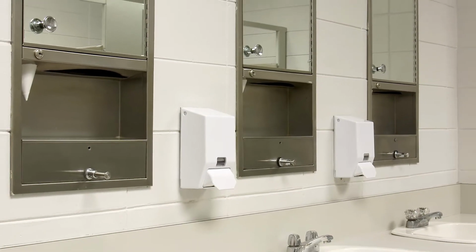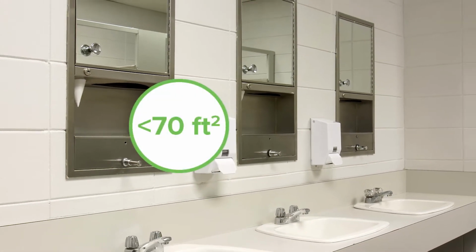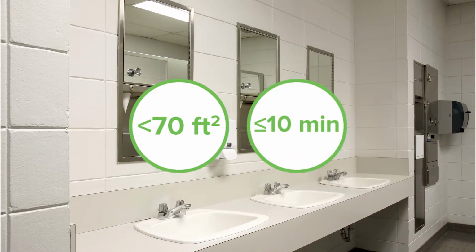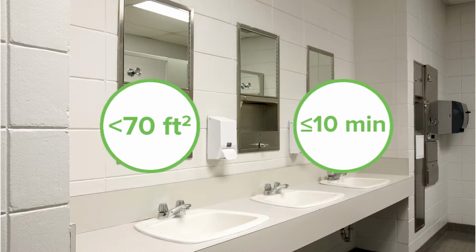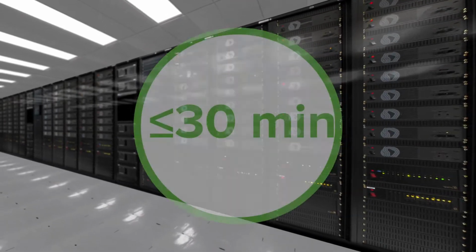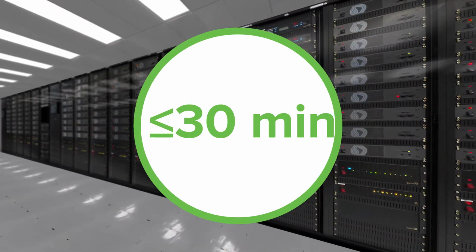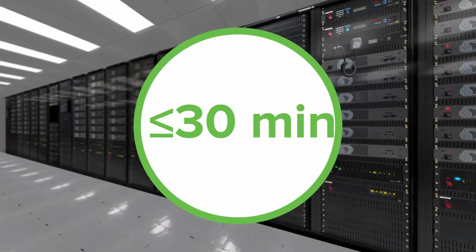Countdown timer switches can be used in single-stall bathrooms and closets less than 70 square feet in size. The maximum timeout setting must be 10 minutes or less to comply with the automatic shutoff requirements. These devices can also be used in server aisles and dedicated server rooms. In these spaces, the maximum timeout setting must be 30 minutes or less.